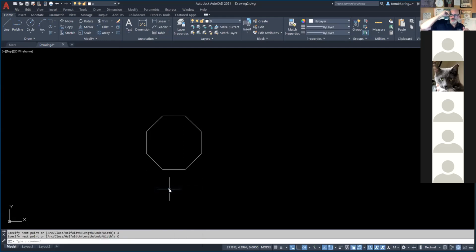So that is how polar tracking works. Polar tracking allows you to create any kind of angular input that you need to make, any kind of model that you need right there, and it allows you to lock in at whatever you set it up as. I want to make sure we went over that again because that's something that you will be using as you go along. It's very useful for not just doing 90-degree angles, but you have to have it for doing architectural plans because you've got to have that 90-degree angle. So 45 will work for our 90-degree angle too, because it's part of that. So we're good to go there.